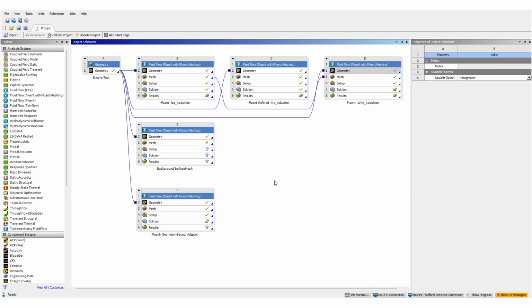So far we have done the initial mesh and manual meshing. This one is about 2500, 2600 cells, and the pressure drop is above 45,000 between inlet and outlet. The refined mesh has less than 6,000 cells, and the pressure drop decreased to above 21,000, so almost 10% decreased.